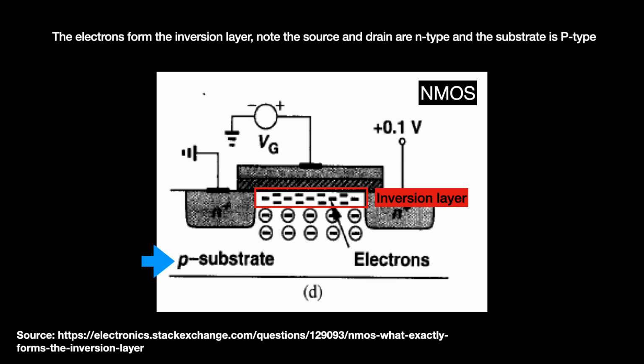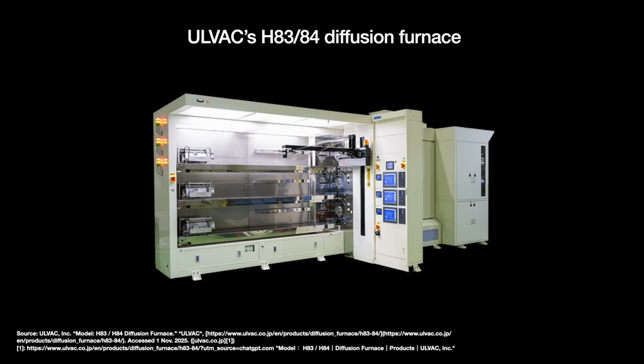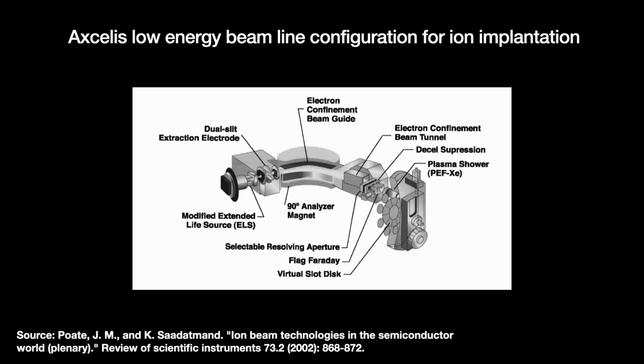In the old days, doping was done with thermal diffusion, which is a fancy name for shoving the wafer into a furnace with the liquid dopant and heating it to 900 to 1200 degrees Celsius. If all goes well, the dopants diffuse into the silicon. Thermal diffusion was later replaced by ion implantation. In it, we energize ions of the dopants and fire them in the form of an ion beam. The dopant ions smash into the silicon atomic structure like little meteorites, implanting themselves.